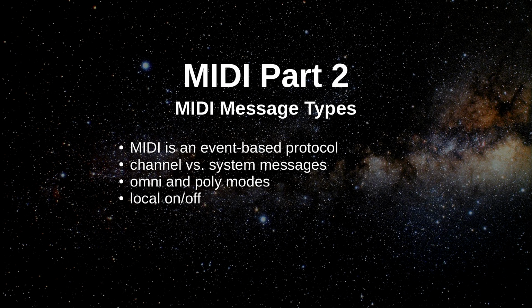So there's four main points that I want to cover today, talking about message types. We'll get into the specific message details later on in a future video, but these are the main four points that I think fit, which is that MIDI is an event-based protocol. We'll talk about what that means. Channels versus system messages. Omni and Poly modes. These are a little bit old-fashioned, but you still will run into it from time to time. And also local on and off. And if you're new to using hardware synthesizer keyboards with your computer or with another sequencer, then this is an important point. So let's go over to the bench, as usual, and we'll get right into it.